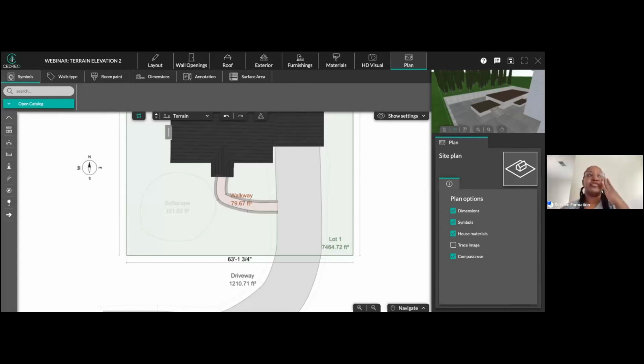So for example, if you've created slopes using shapes, the current plan will activate, but you will have to go back and delete all the shapes that you used to create the slope and these different things. And yes, you can add the stairs to the deck. I'm not sure if you saw how I did that, but I added the stairs in the furnishing step.